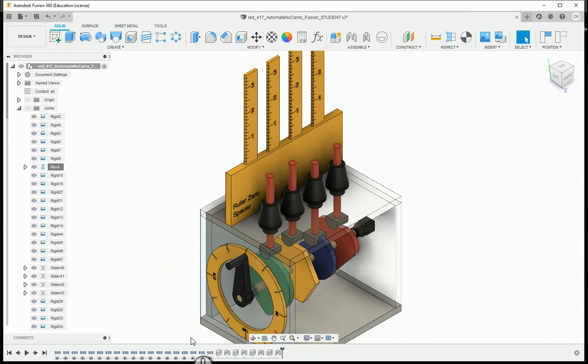Now in this file, you're going to notice there's these little icons that have three rectangles bunched together, and there's a little plus sign down at the bottom to expand. These are called groups. Groups help keep the timeline a little bit cleaner, so you don't have a bunch of sketch, extrude, 3D model feature icons all stretched out across the bottom of your screen. And I'll show you how to put a group together.